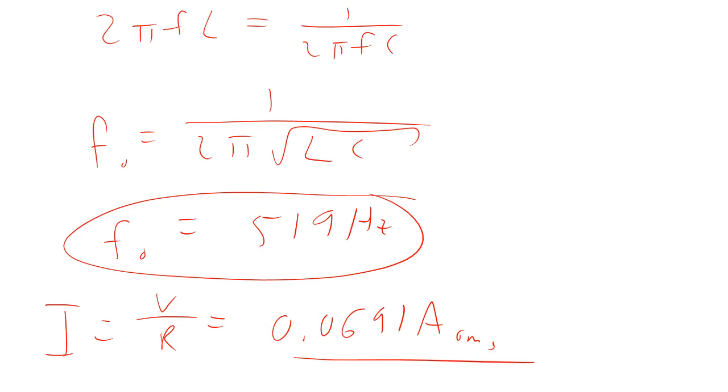Anything else, and you're not at the resonant frequency, so it's going to be less than ideal. At 0 hertz, you get no current, and at super high frequencies, you get no current because of the inductor and capacitor fighting you.